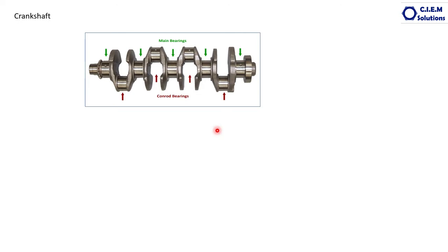All these are mixed in proportion as per the metallurgist's design, and this is made through the forging process. Blocks are made with the casting process, whereas the crankshaft is made of medium carbon steel mixed with some other metals proportionately, made through the forging process. Forging, finishing, heat treatment, etc., is done.